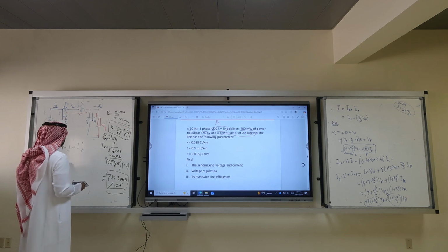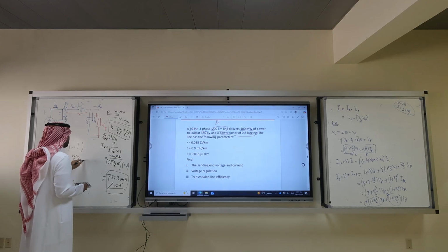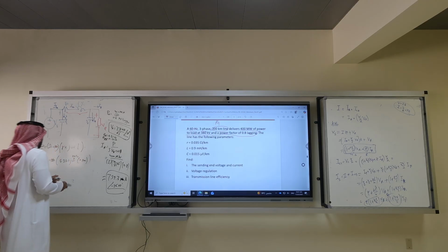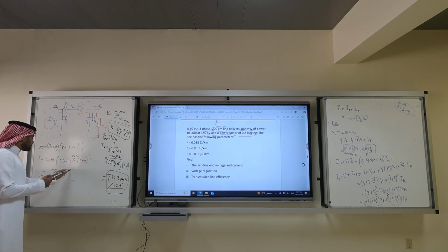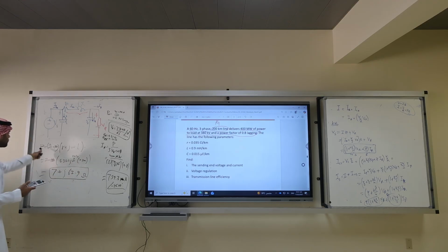What is the R? 0.035 plus j omega, 2 pi 60 times the L, 0.9 milli. Just do it by calculator. 200 times 0.035 plus j times 2 pi times 60 times 0.9 milli. You should get 7 plus j times 67.9 ohm. So this is your Z.